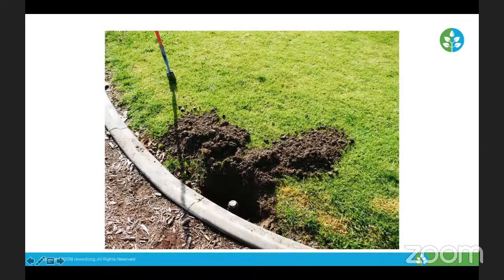One of the things I talked about was tilted sprinklers. This happens quite a bit. This is here at our park. I was doing an irrigation evaluation here at our park, which I do once a year, and I noticed that some of the rotors, just from wear and tear, started tilting, which makes our distribution uniformity go down quite a bit because it's not applying water evenly. It's spraying shorter because it's tilted to the left, and then spraying up and misting. So there were a couple of issues.